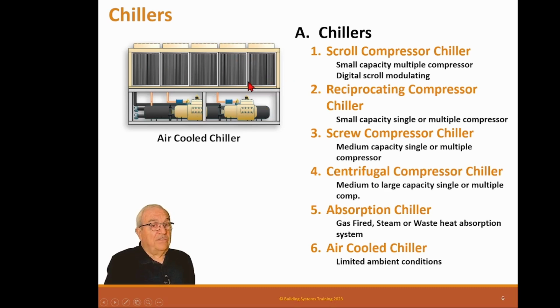The limitation of these, of course, is they don't work very well in high ambients. If you have a high ambient of 110, 115 degrees, these are not your best choice. You need to have a water-cooled system. That's the only problem. Now, if you live up north where it never gets above 90 degrees, these are really a nice choice, and they're mainly used there.